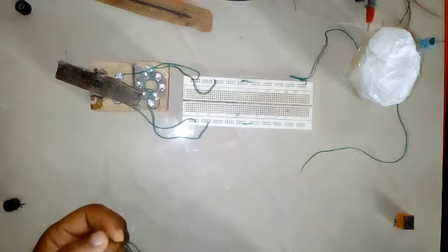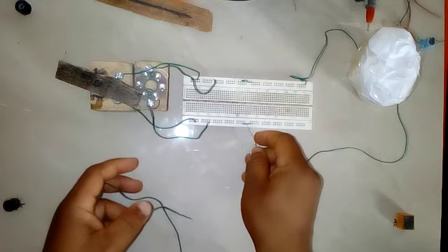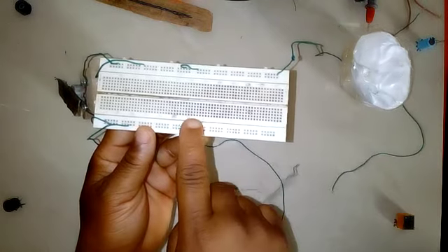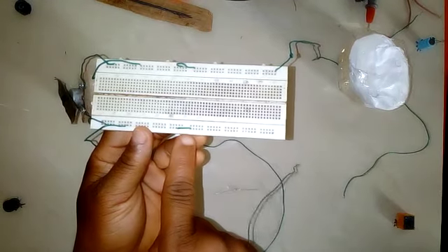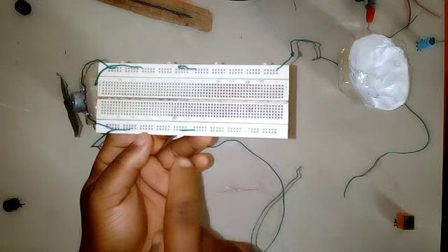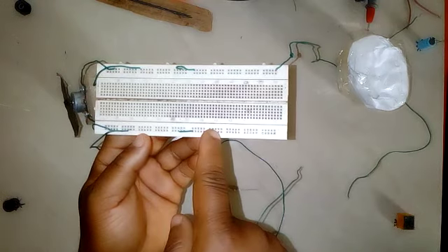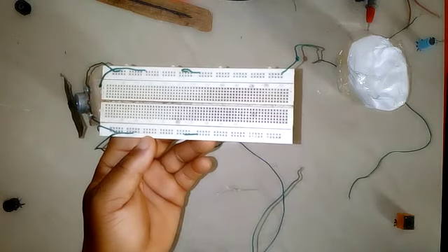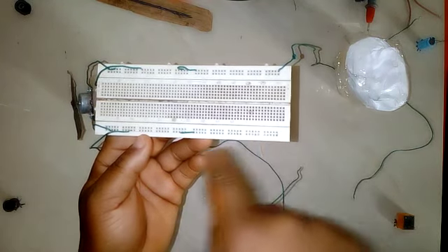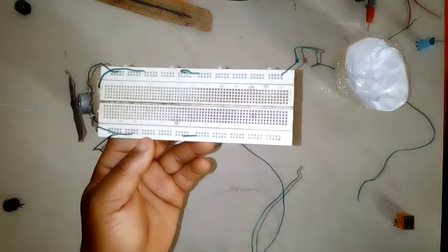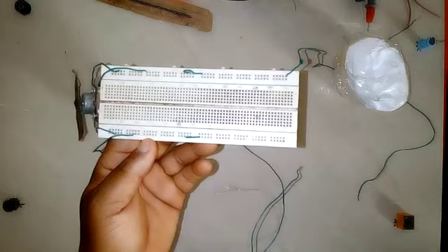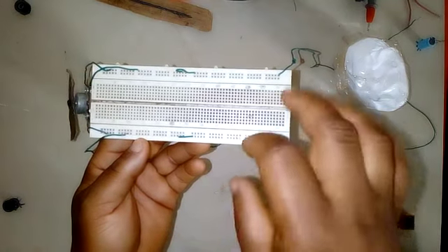So you see my jumper cable here. I'm going to, you notice that it renders these 2 sections continuous. Now instead of the jumper cable, I'm going to put the potentiometer there so that we're able to vary the current running through the circuit, by which way we will regulate the speed of the DC motor and the brightness of the LED. So instead of the jumper, I'm going to insert the potentiometer here.